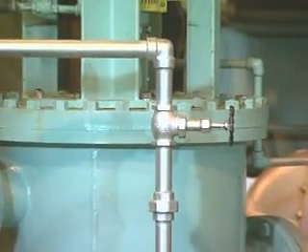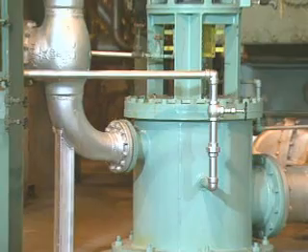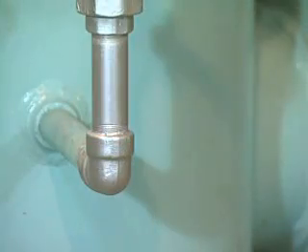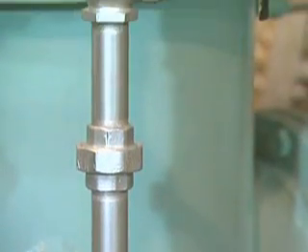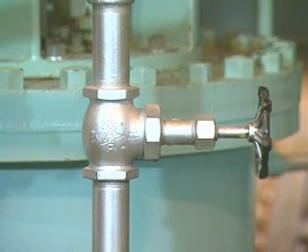Condensate pumps usually have suction and discharge vent lines that are connected to the main condenser. In most cases, the valve in the discharge vent line is closed after the condensate pump has been started and is operating normally.